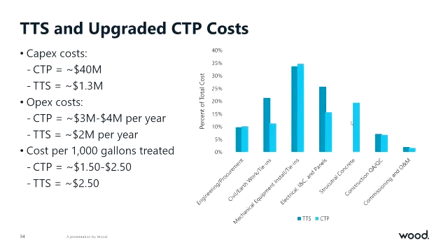The OPEX for the CTP ranged from $3 to $4 million for the upgraded plant. It's a big range because that plant was designed for 2,000 to 8,000 gallons per minute. The temporary system in comparison is about $2 million per year. So the CTP is about $150 to $250 per 1,000 gallons treated, depending on the flows, and the TTS is about $250.